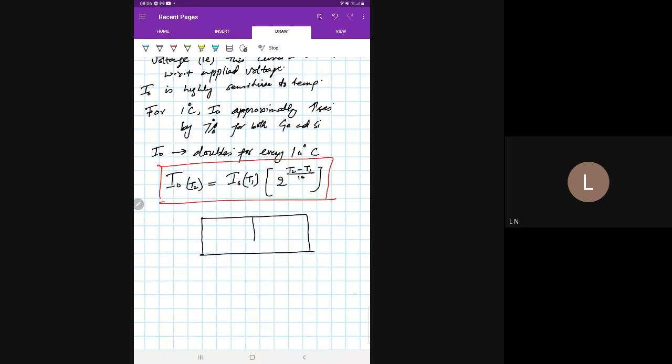If we have a PN junction like this, this is the width of depletion region, and we know that width of depletion region will be larger, and we are applying a reverse bias. This is P type here, this is N type semiconductor on this side. We are applying a reverse bias, that means a higher potential here on N side and a lower potential on P side, okay?